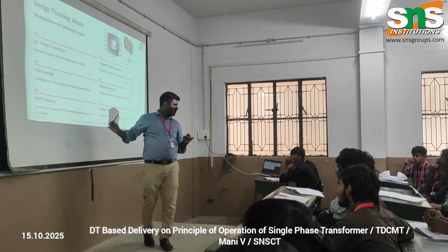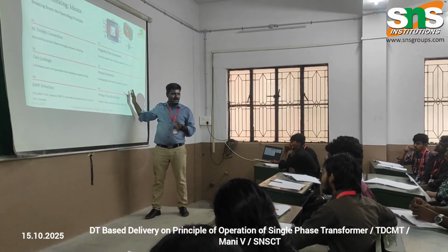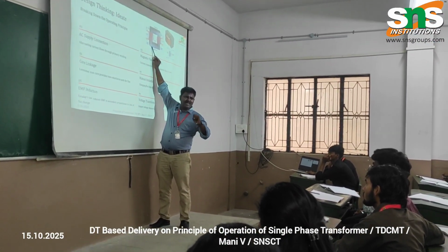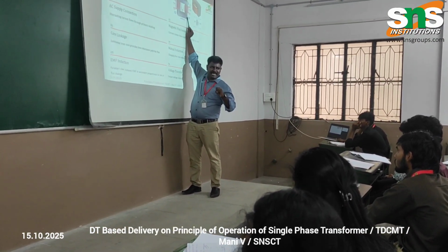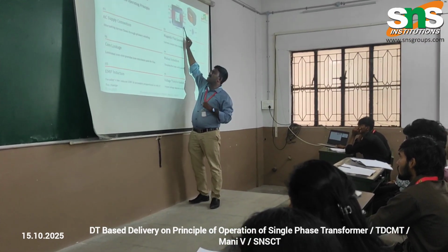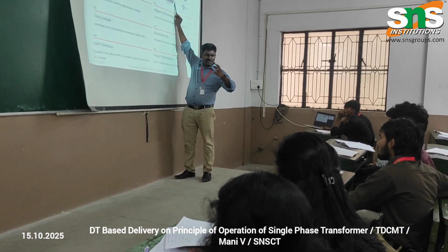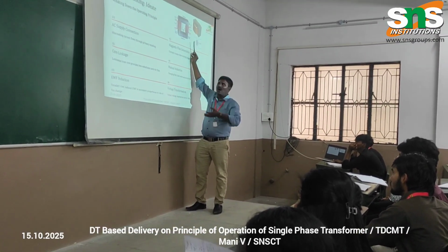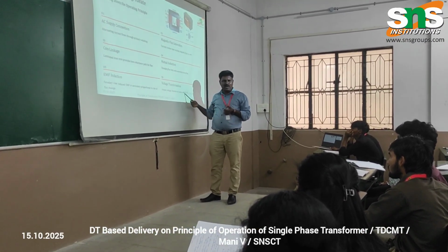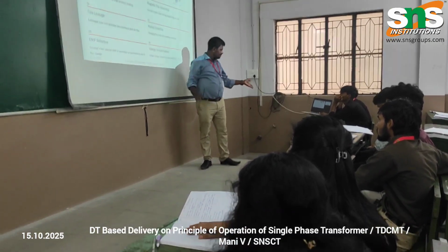Okay. So this is the working principle. After giving the AC supply, it starts producing the flux. The produced flux will be transferred to the secondary winding through the transformer core, and according to the mutual induction, because of the change in flux, the EMF will be induced and delivered to the load. According to the load requirement, we can adjust the output voltage.